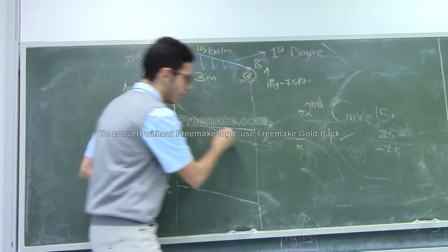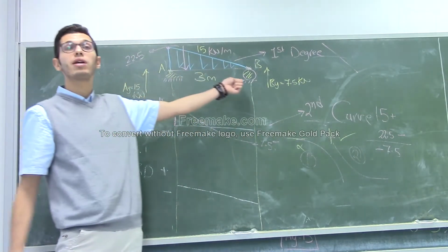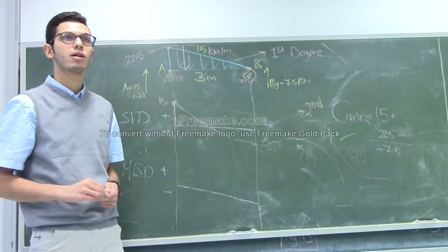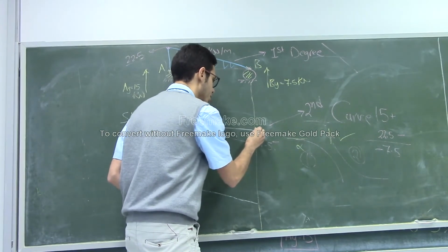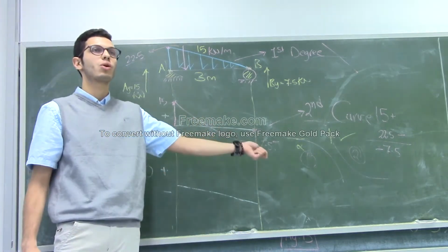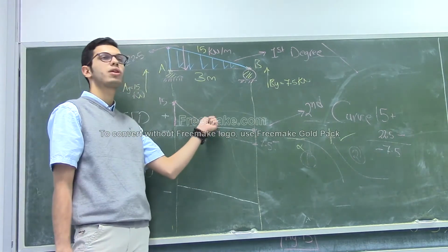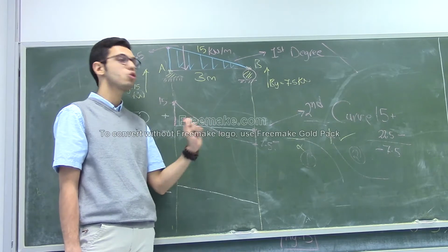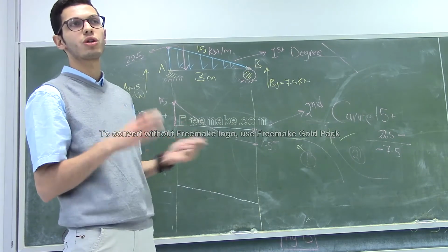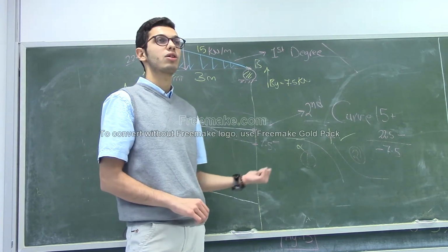So, like this one, now I'm at minus 7.5. At the point B, Vy is equal to 7.5 upward, right? So if I go up, I will end with 0. That means my solution is correct. If you end with a 0, that means your solution is correct. Because as I said before, always on the shear diagram and the moment diagram, you should always end with a 0. If you end with another value, that means your solution is incorrect. Okay. Again, up to this point, does anyone have any questions?